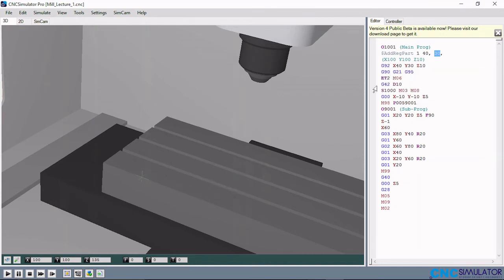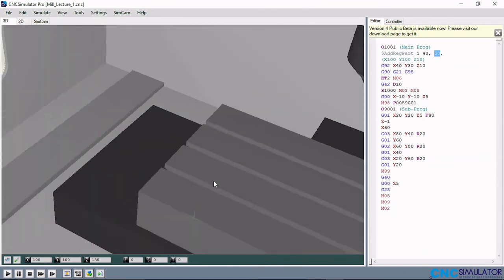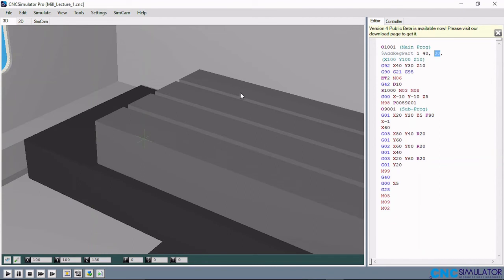Why that is important is because at the time I want to set my 0 offset, the same way we did for the lathe, when I want to transfer this crosshair to the origin, where I want my origin to be on my workpiece, I will need this point to locate the origin. So G92 is the 0 offset, and I'm putting the 0 offset. Now I want to move this cursor from here to the workpiece.